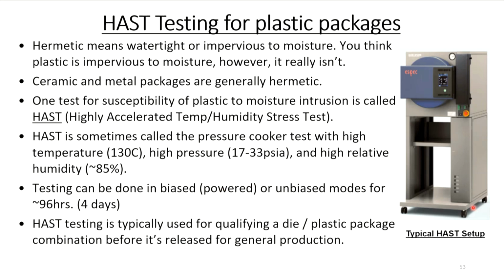This test can either be done in biased mode or unbiased mode. And typically it's done for periods of 96 hours, which is roughly 4 days. Now, HAST testing is typically used to qualify a die/plastic package combination before it gets released to general production. I show a typical HAST setup on the right over here.